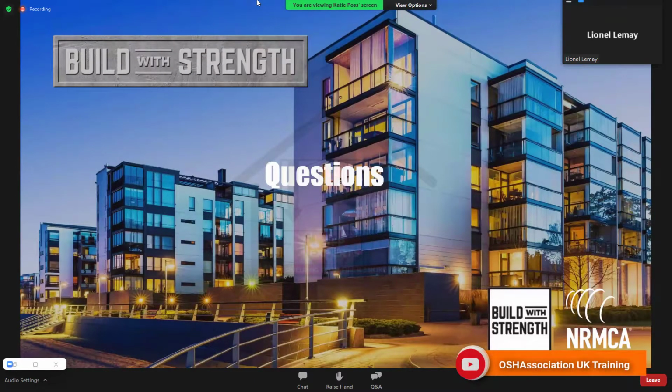And if you're collaborating with them in the design stage, that would be another source of data. There's the EC3 tool that Katie talked about as another potential source, but make sure that you're using data that's from your region, as specific as possible, because the environmental impacts do depend on the local materials that are available to producers.